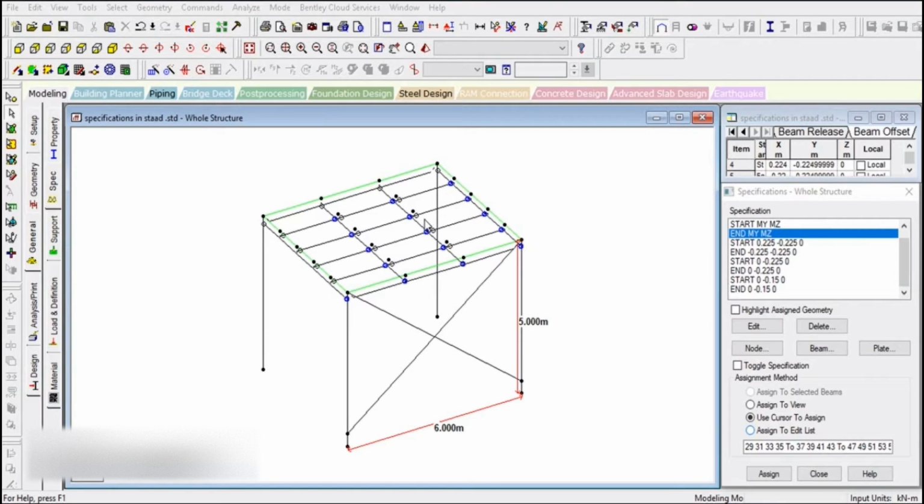But before doing that, I would like you to please save as this model, because we will not use this plate in our final structure. I'm just sharing this for your introduction to how this plate meshing and deck slab system works.